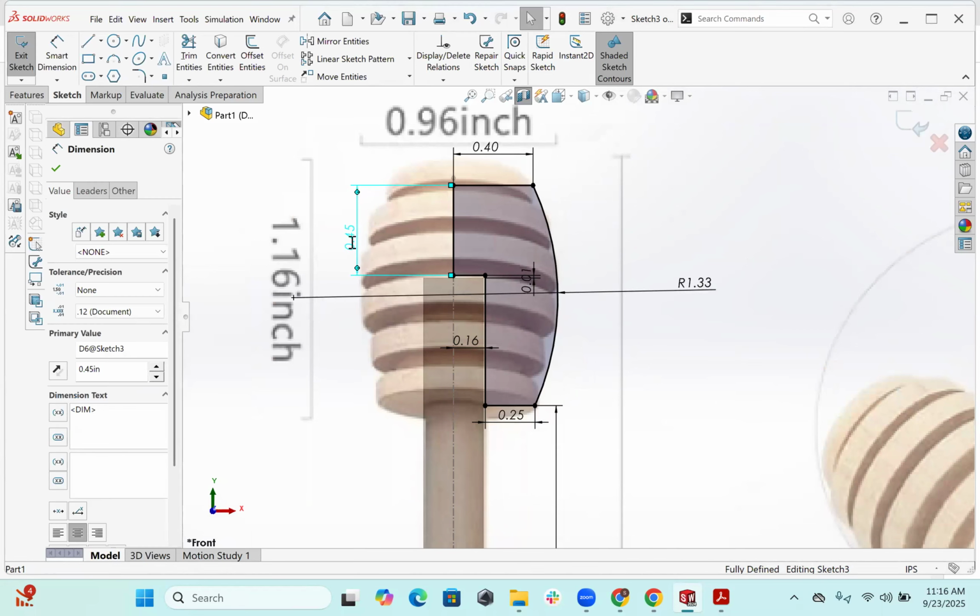Let's now go through our fillets. Because we have two separate bodies here, we can see that's our first body and second body. We can fillet the hard edges on the first body together and fillet the other body together. So you cannot combine your fillets. And we're going to start with the first body.